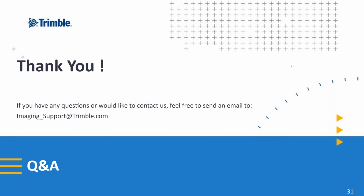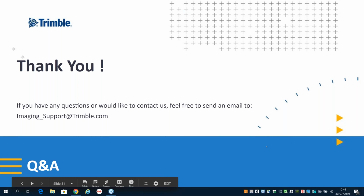All right, Yoni. I think we have a couple of questions here. I'll try to go through the list of questions and comment. The first question: can I use non-Trimble base stations? Yep, of course. If it's a correct format for post-processing, for example RINEX, you could use non-Trimble base stations.